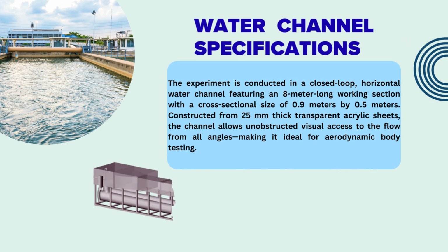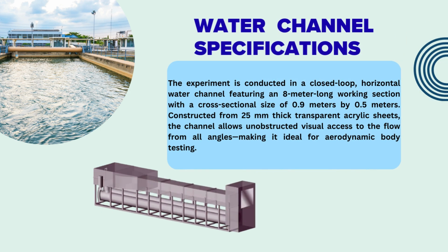Water channel specification. The experiment is conducted in a closed-loop horizontal water channel featuring an 8-meter long working section with a cross-sectional size of 0.9 meters by 0.5 meters. Constructed from 25 mm thick transparent acrylic sheets, the channel allows unobstructed visual access to the flow from all angles, making it ideal for aerodynamic body testing.